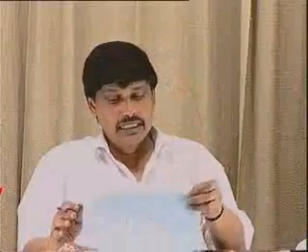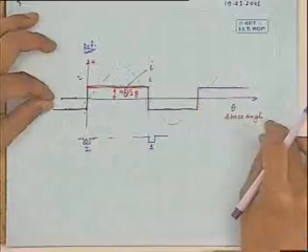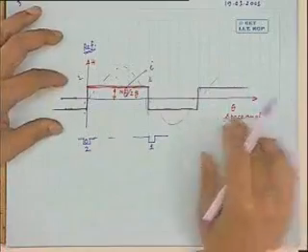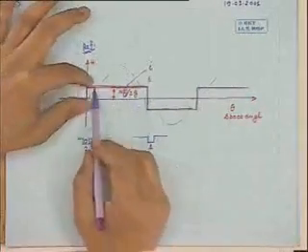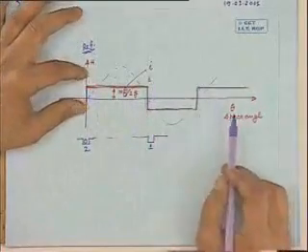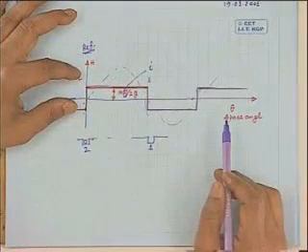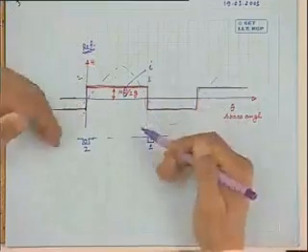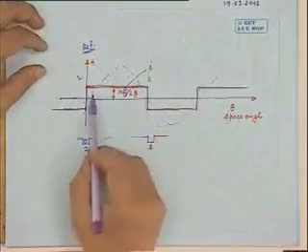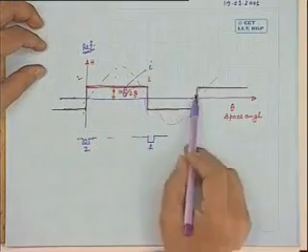But amplitude depends upon Ni by 2, is not? Ni by 2 is the amplitude of this one. This I now becomes a function of time. When I is 0, this will be a flat line. When I is maximum, this will have its maximum amplitude, rectangular shape. When I is negative, the direction of MMF itself changes.